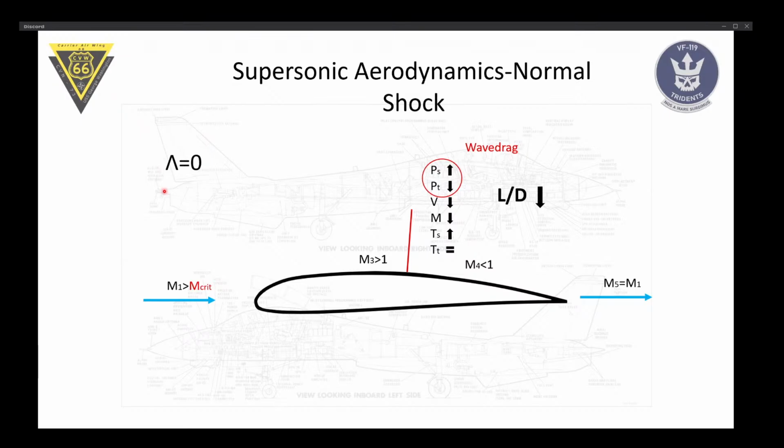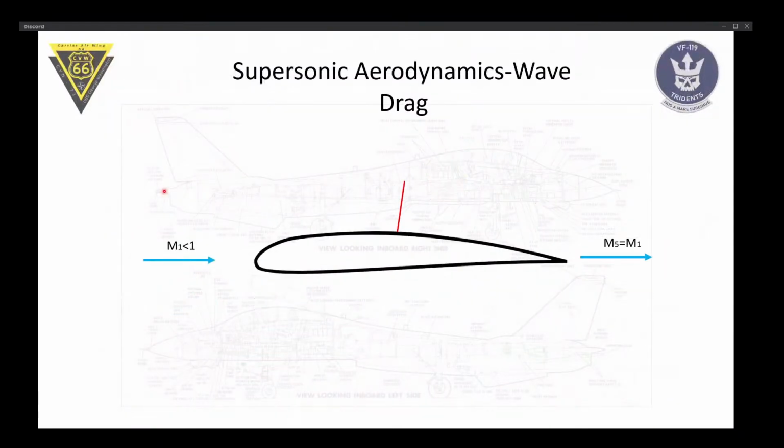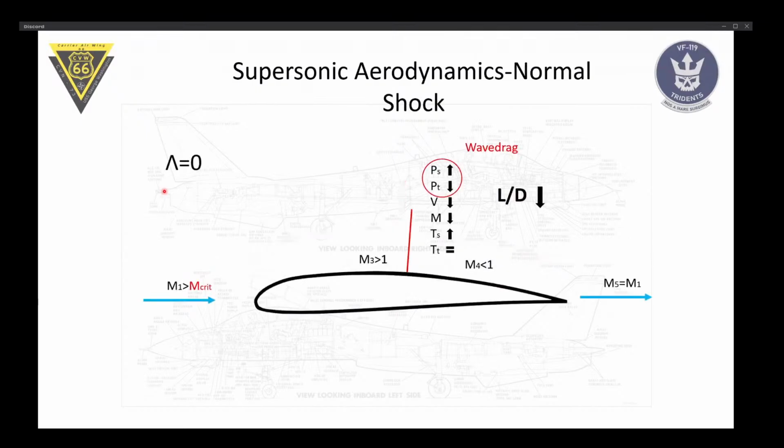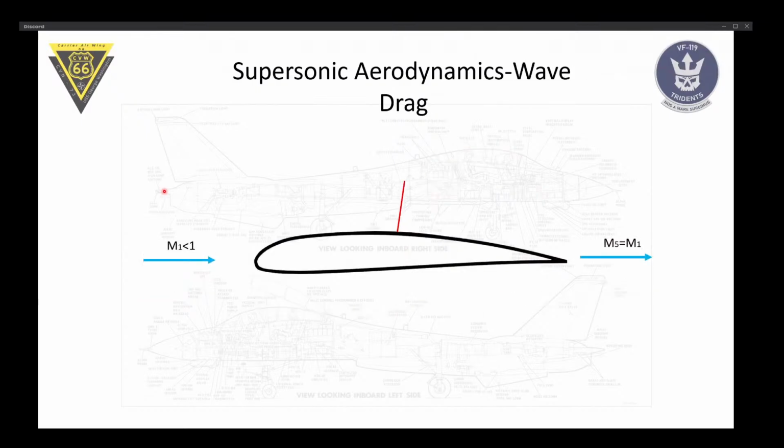Now at some point in the 30s, I think, somebody came up with the concept of a swept wing. So we basically take our... before I come to that, I just wanted to show you how this develops. So we have a shock, and as we get faster, the shock moves backwards and gets stronger, and on the underside we also get a shock, because the air is also accelerated on the lower side of the airfoil, but slower than on the upper side. So on the lower side we also get a shock, and as we pass Mach 1, we're having 2 shocks at the back and a so-called bow shock at the front. That's basically the configuration you would see in supersonic flight.